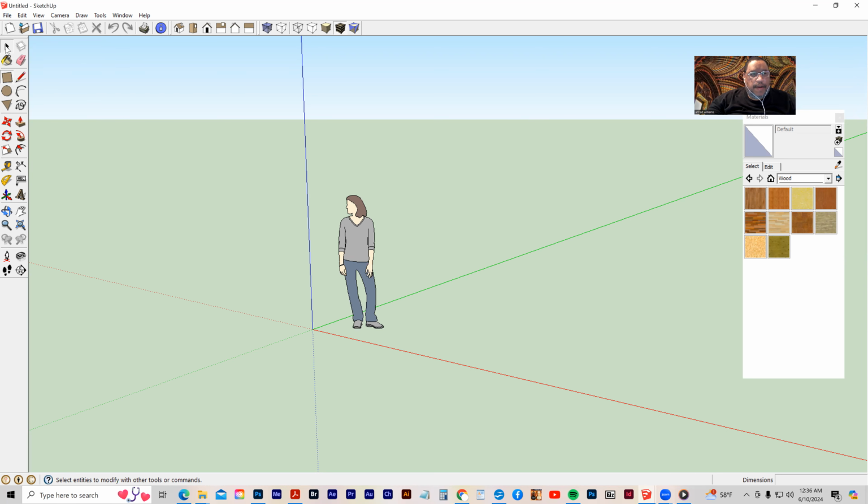Let's delete the lady. I'm going to grab my selection tool, click on the lady, delete her. I'm going to grab my rectangle tool and draw a rectangle that's 20 feet by 10 feet. So I'm going to click, drag out, and type in 10 apostrophe, comma, 20 apostrophe, enter.